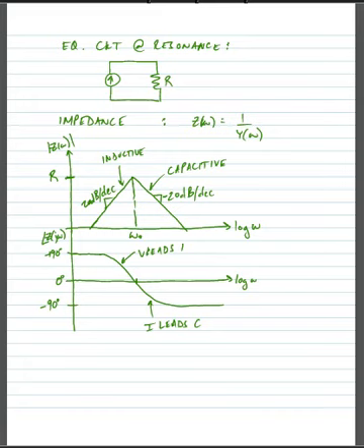Next, we're going to look at some metrics about this circuit, about the energy storage in this circuit. Functionally, what's happening when we use these circuits is that energy sloshes back and forth between the inductor and the capacitor every cycle, and some of that energy is lost to the resistor. In an ideal circuit where there's no resistance, the energy would slosh continuously back and forth between the inductor and capacitor, and we would see an oscillatory behavior.